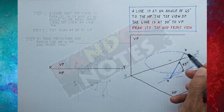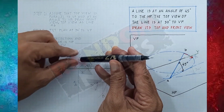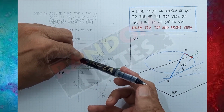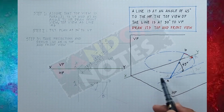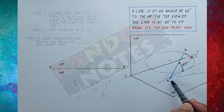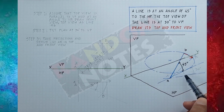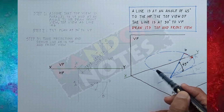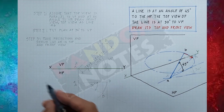This is the line AB, which is at 45 degree to the horizontal plane. Anchored at point A, if I turn it around, the height of this point will remain the same. This height is depicted by this circle out here. So if I anchor my line at point A here, and if I rotate it, the angle will always remain at 45 degrees. I have to rotate it in a manner that the top view of this line makes an angle of 30 degrees to the vertical plane and then take the projections. This is our XY line. We'll do it in 3 steps.